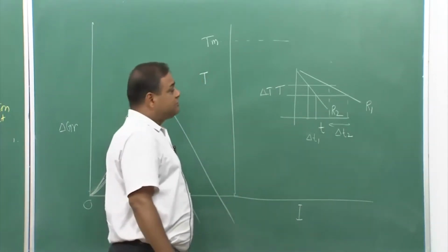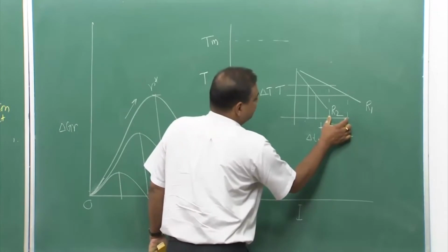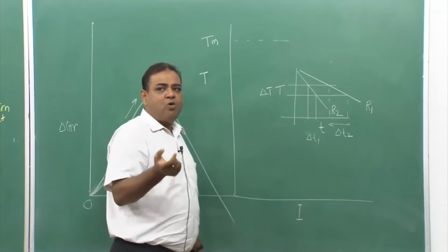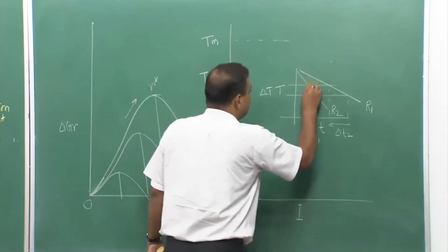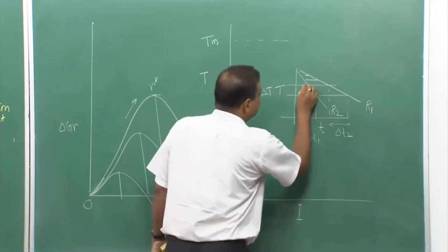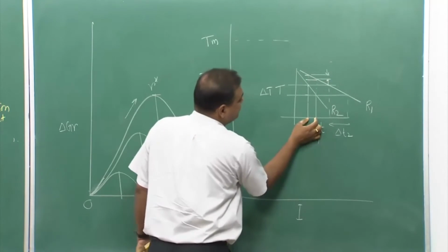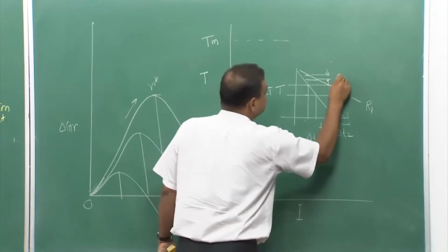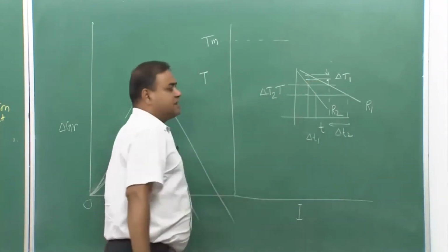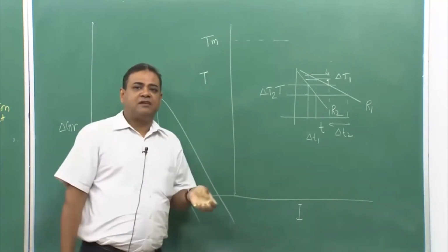is slow. So, that means in other way, let us say I fix my delta T1, let us say this one I have fixed. So, I would like to see in a similar time duration how much del T I can achieve. So, now if I go there, here I am achieving this much, but here I am achieving this much. If I try to follow the same duration, this much is the del T1 and this is delta T2, in case of higher cooling rate. So, that means higher cooling rate gets me higher del T, that means higher undercooling.